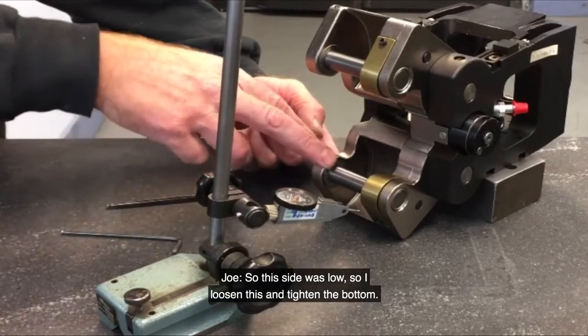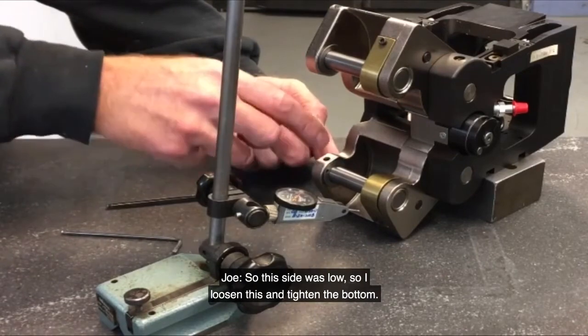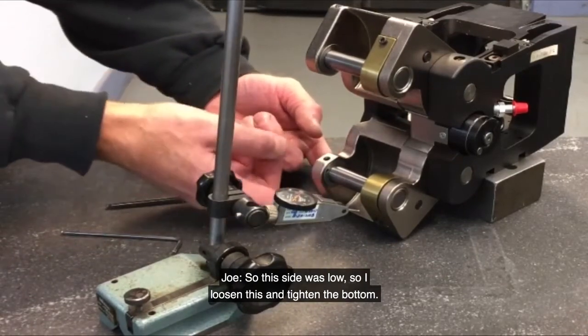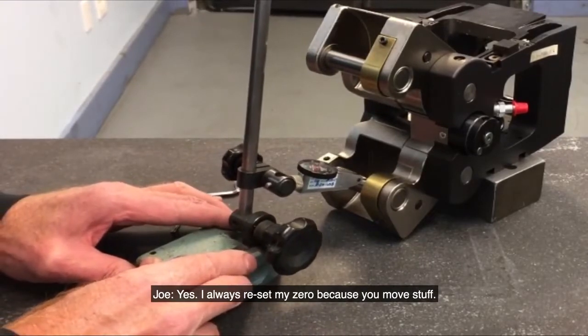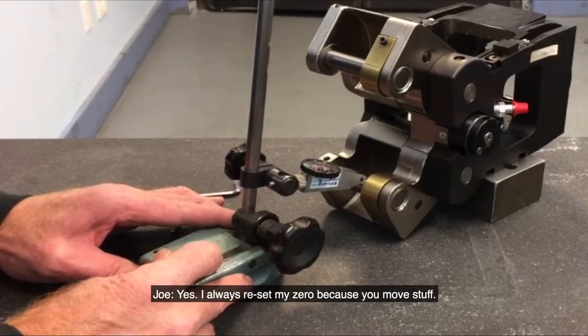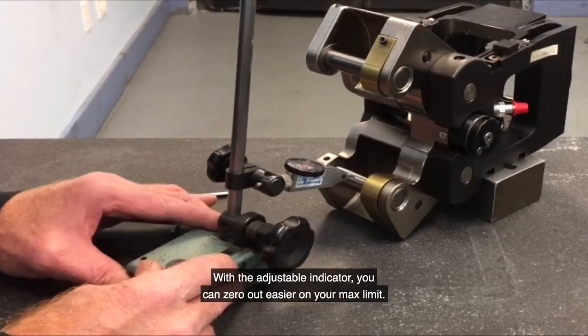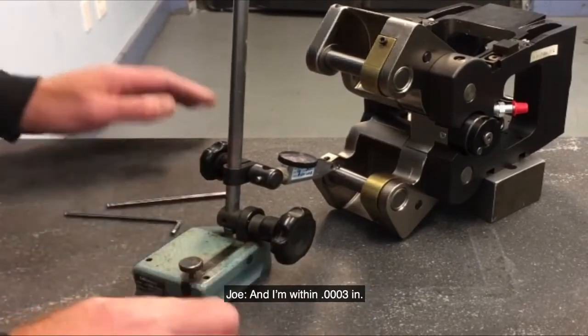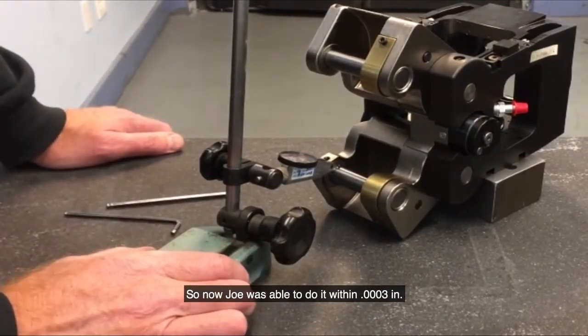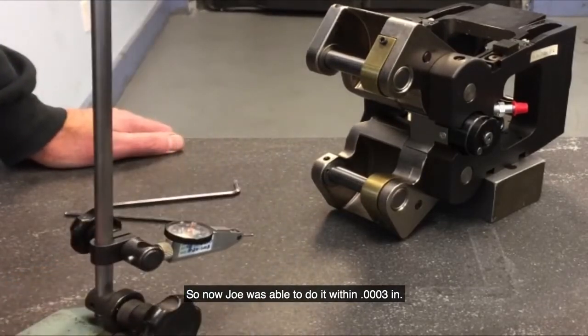So this side was low, so I loosened this and tightened the bottom. And now you're going to re-indicate. Yes. I always reset my zero because you move stuff. With the adjustable indicator, you can zero out easier on your max limit. And I'm within 3/10. So now Joe was able to do it within 3/10.